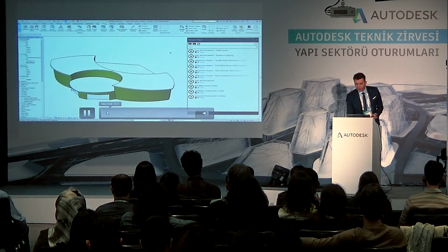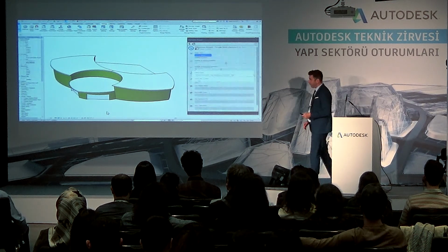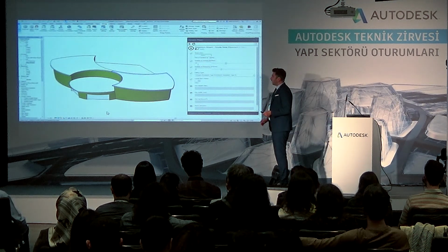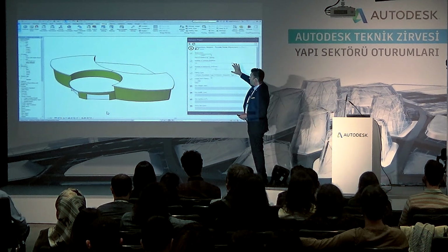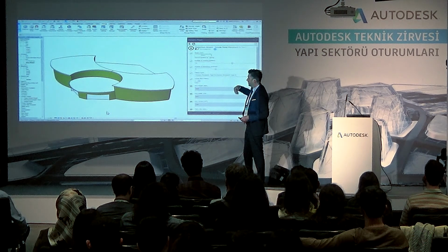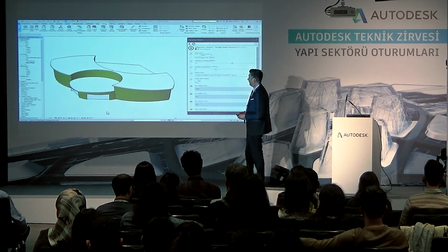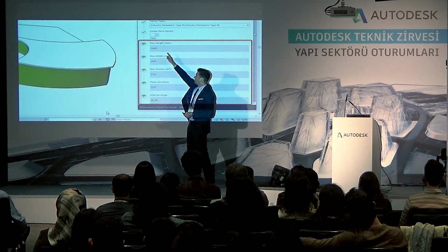Okay, so this is where we can start to place the panels. Of course, first, using Dynamo Player, which can read that script, we can directly from the Revit interface generate the layout. And we can turn on and off creating the panels.